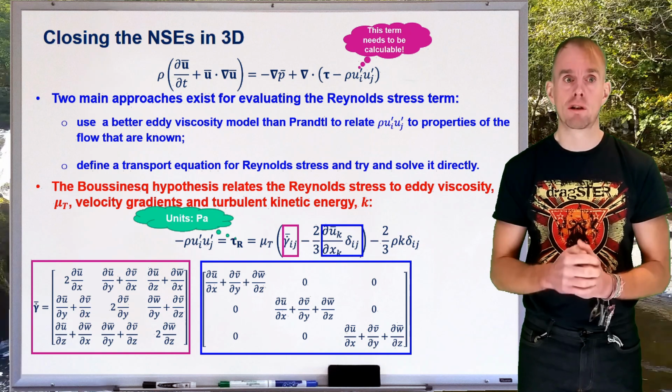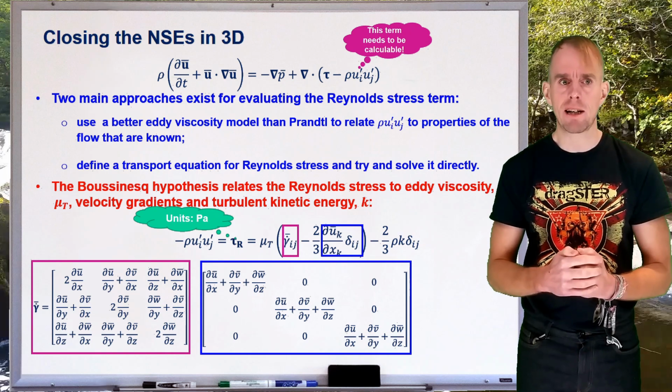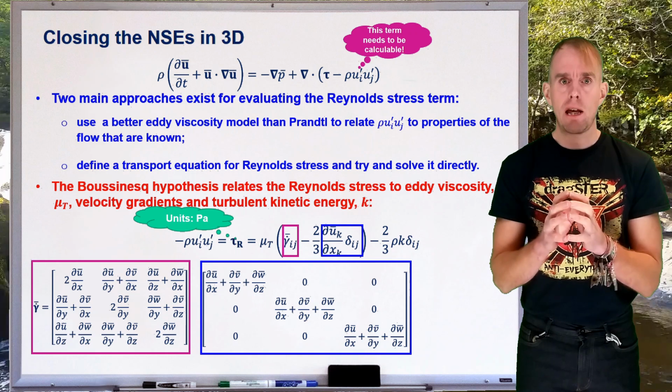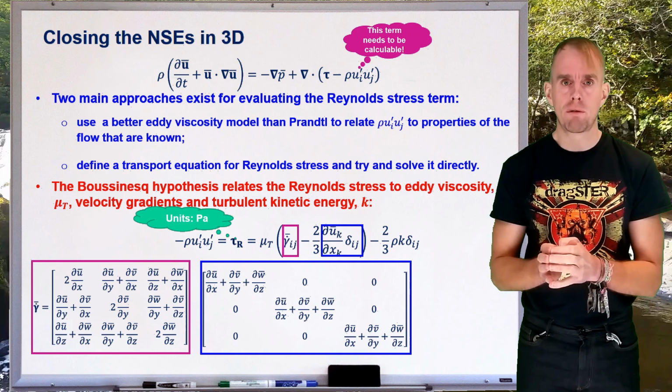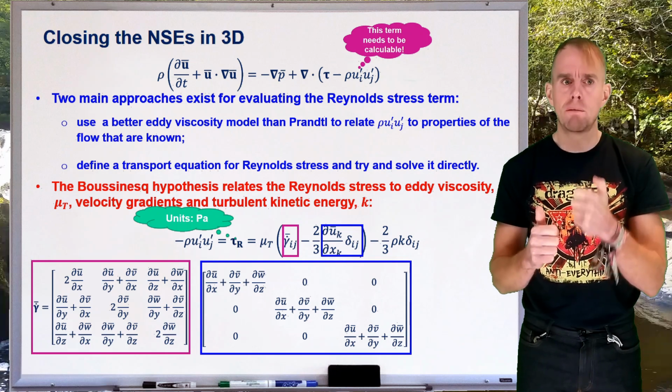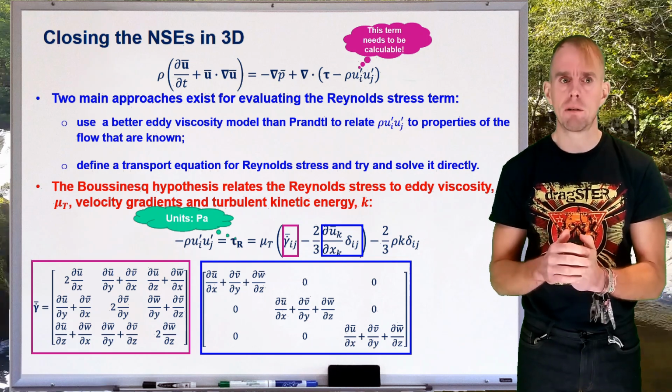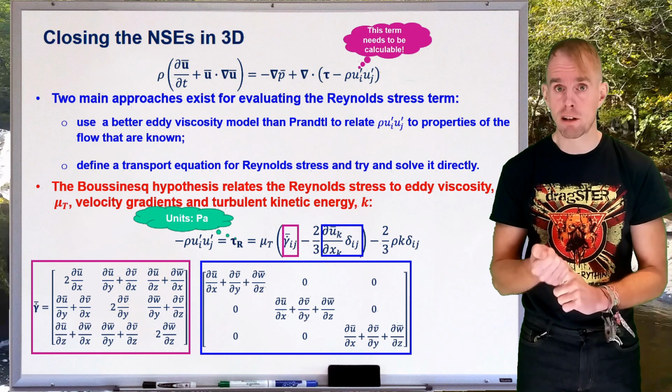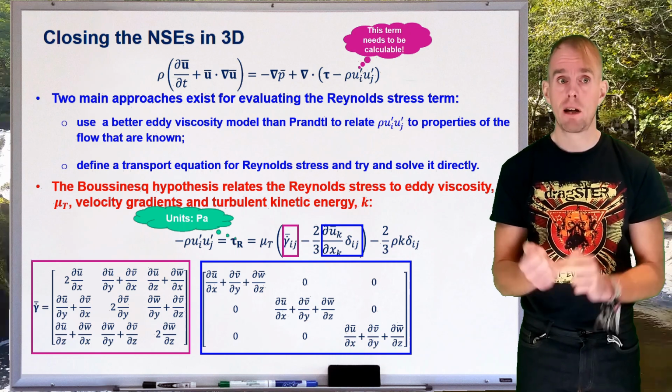So let's look at that partial derivative, du bar k by dx k. Well, if I count from k equals 1 to 3, for each individual value of k, that's each of the individual components of the vector u. And so that's going to be an x direction velocity, a y direction velocity, and a z direction velocity.